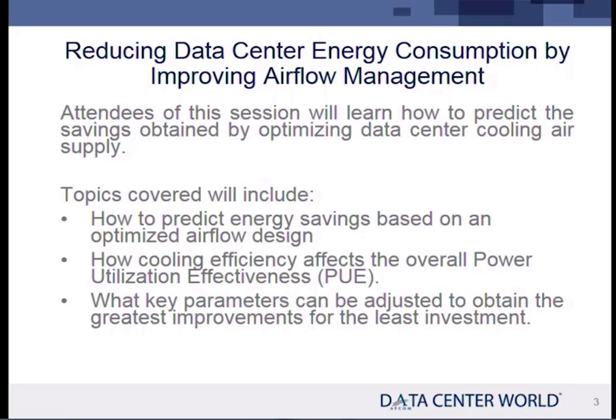So what we're going to talk about today is how to predict energy savings by optimizing airflow. Most all of you have air-cooled computers. Liquid's great. Liquid's a little more expensive. They'll always be air-cooled because of the economics. Liquid's just going to be more expensive. That's just the bottom line. So you're always going to be dealing with airflow. Even in liquid systems, there's airflow. So, at some point, particularly with rear door heat exchangers, there's airflow. So we're going to be talking about airflow today.